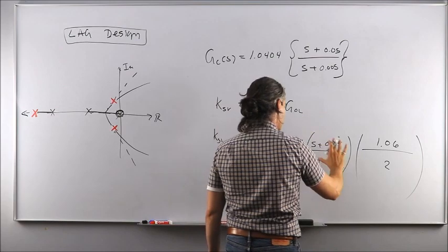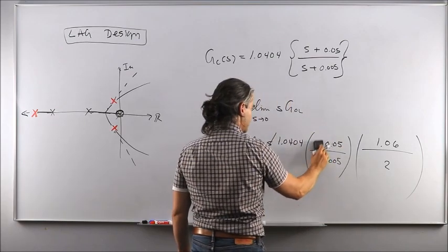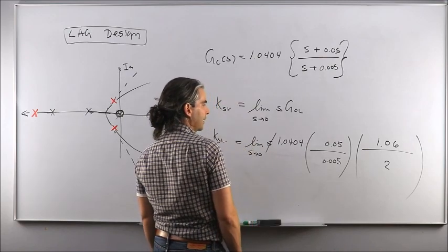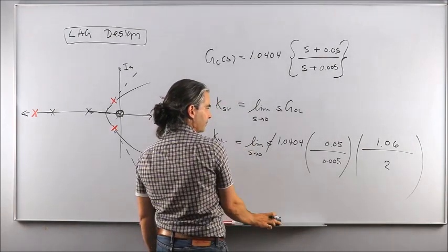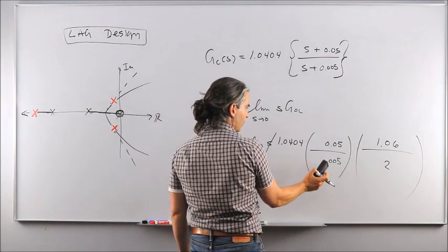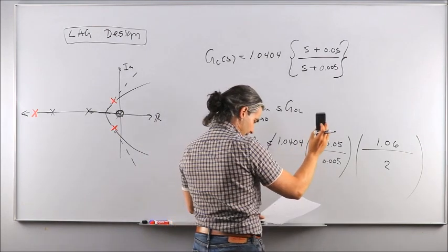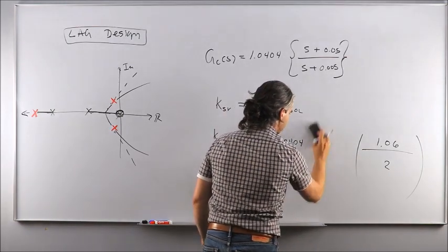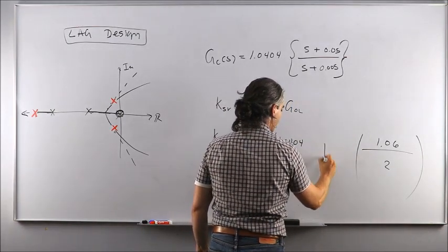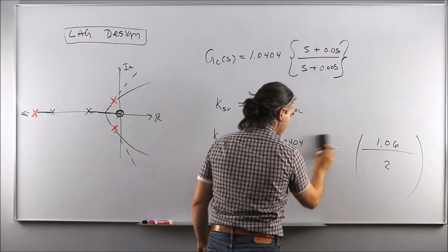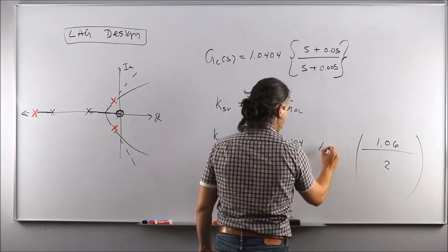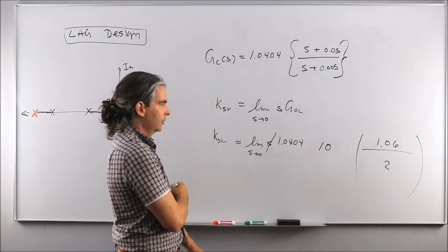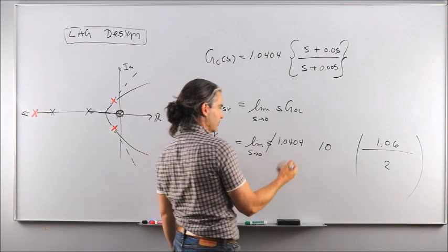Now, by virtue of adding this, S is equal to 0, S is equal to 0, aha! Now I see where the beta factor comes from. Because the ratio of this over this gives you 10. Right? Because you had ensured beta of 10. You had ensured to locate the position of your pole and zero to satisfy this ratio of 10.